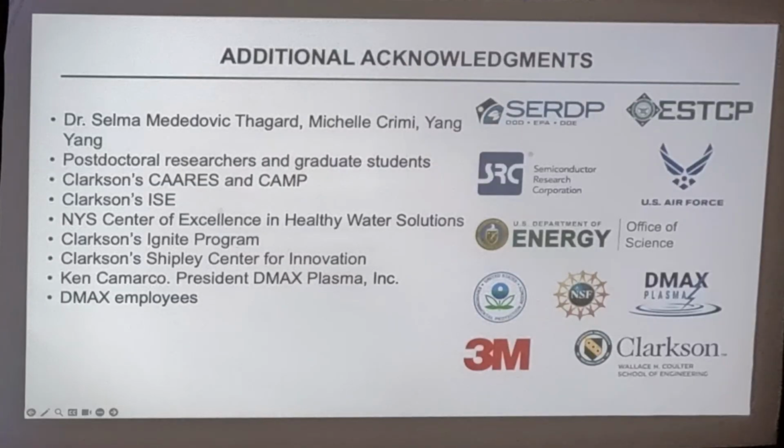But if you have a groundwater contaminated with a chlorinated solvent, for example, if you look around those sites, you can find bacteria that can utilize the chlorine to grow, either directly or by co-metabolism with something else. And environmental engineers have cultured those bacteria, and now we can use them to clean up other chlorinated sites. So it's a great way of bioremediation, a well-known strategy.